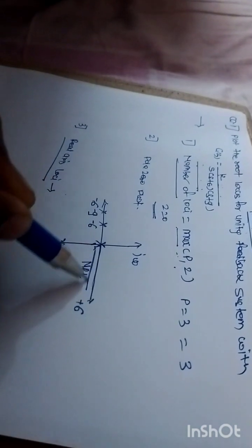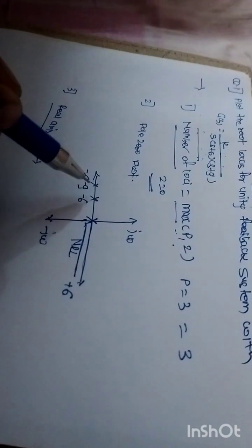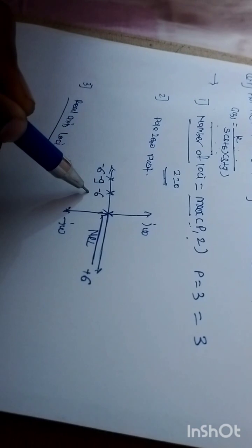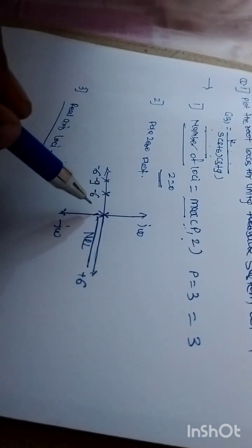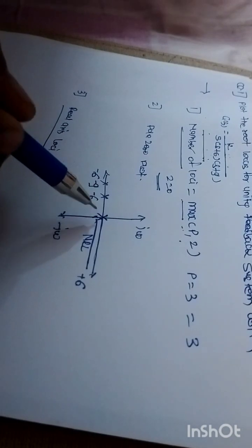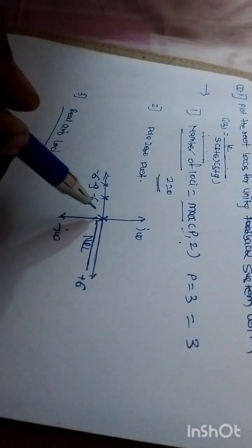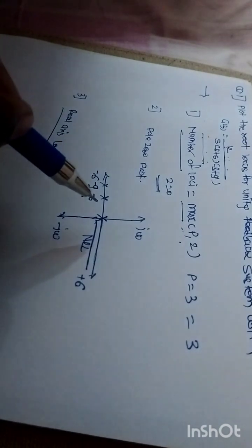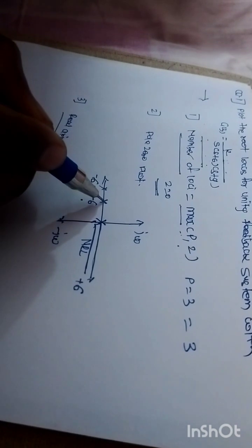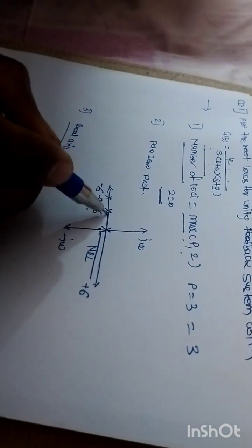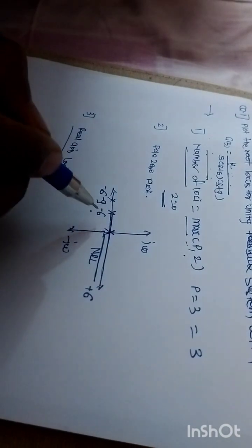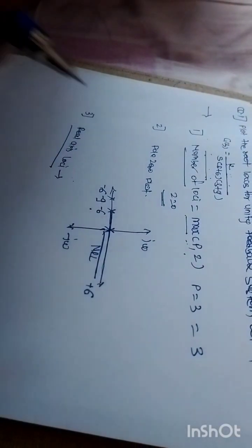in this portion, right? And when we consider the second pole, which is located at -6, to the right hand side of this -6, how many poles do we have? We have only one pole, which is located at the origin, right? This means if we have an odd number of poles and zeros to the right hand side of the existing pole, definitely we can say that there will be an appearance of the root locus in between this interval, right?